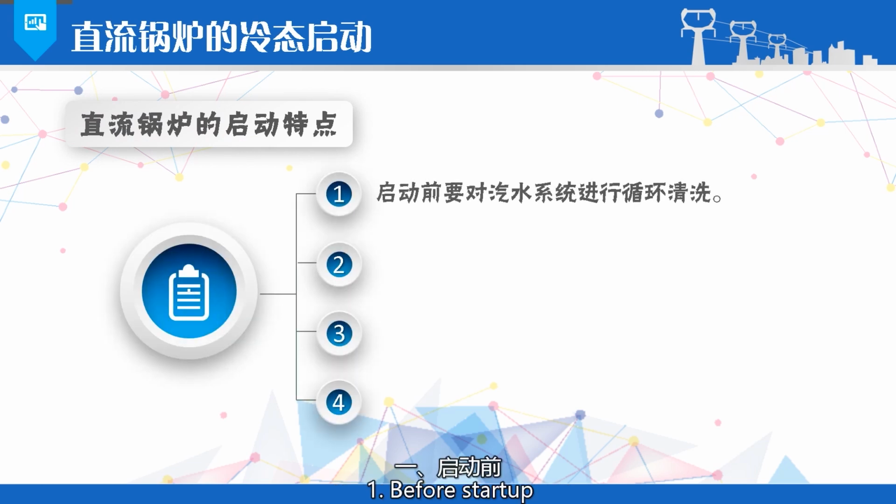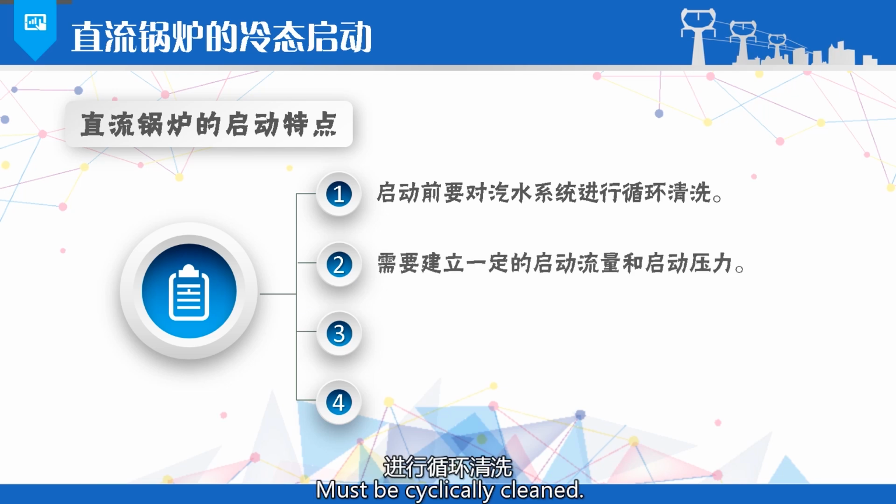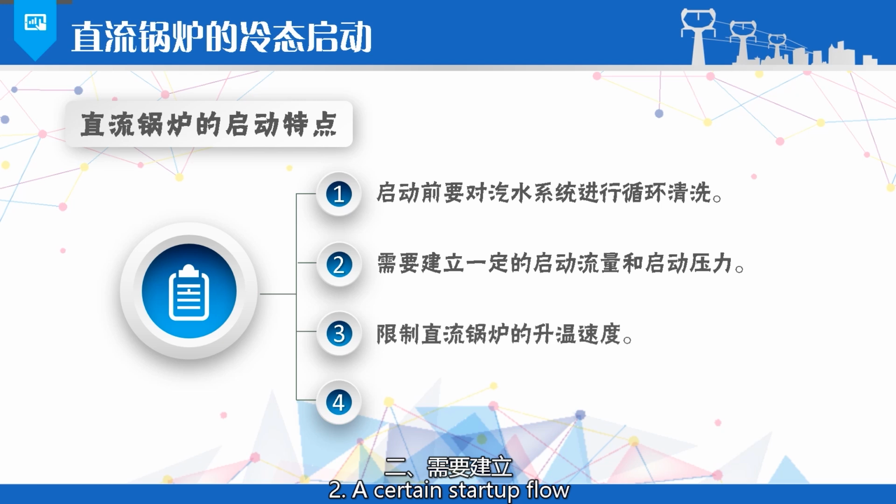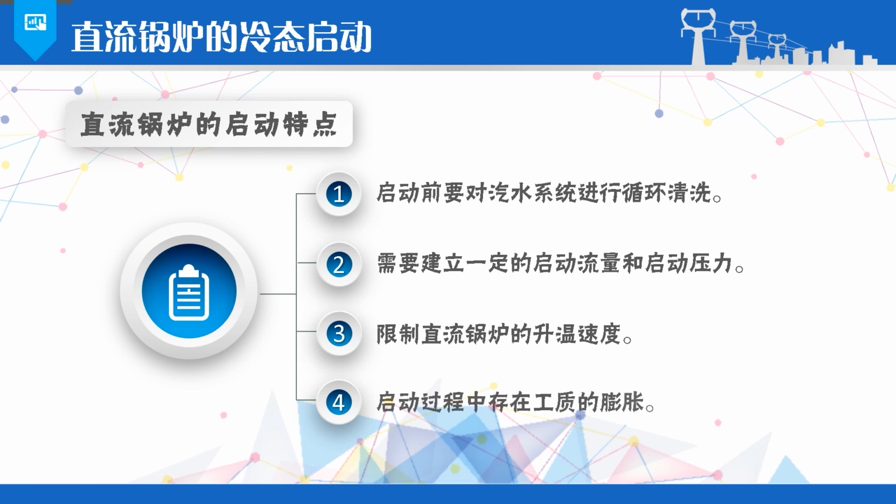First, before startup, the steam water system must be cyclically cleaned. Second, a certain startup flow and startup pressure need to be established. Third, the heating rate of the once-through boiler must be limited. Fourth, during the startup process, there is a phenomenon of working fluid expansion.